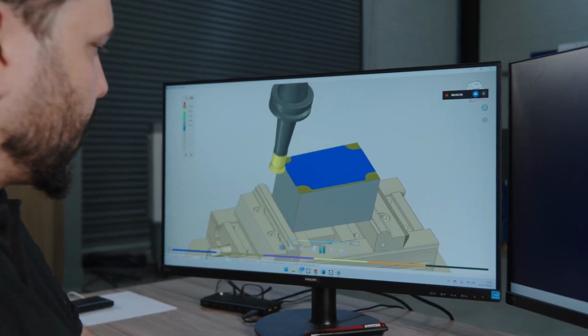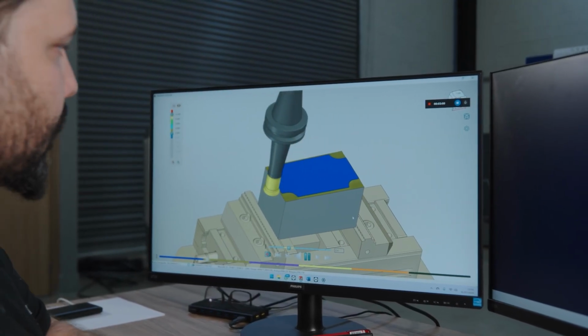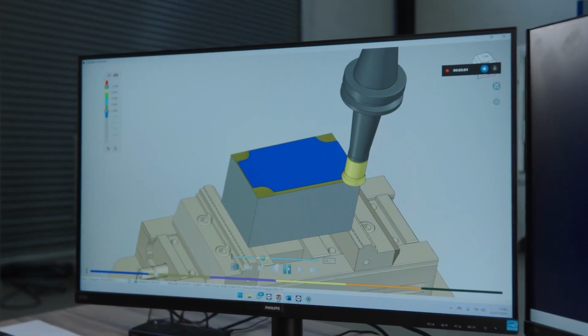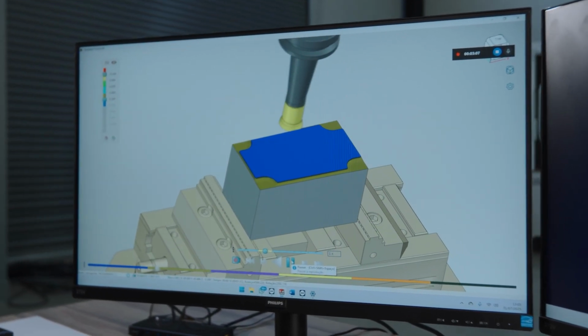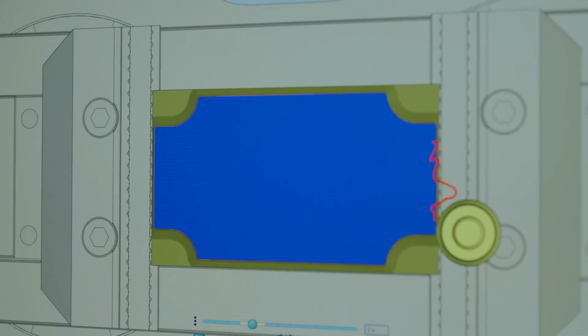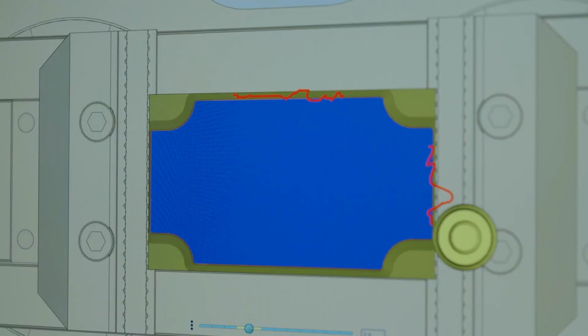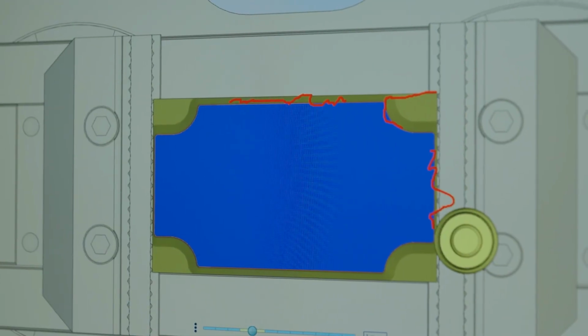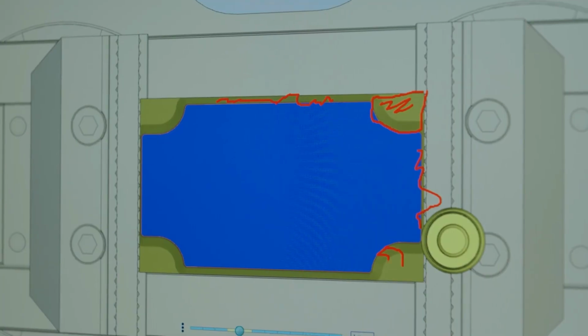Now let's look at a contouring process where this problem is even more serious. Come with me. Here I have a contouring process. You can see that here this problem is even more serious for a few reasons that I'm going to show you now. Notice that in this part I have an area with very little material to be removed. I have an area with a bit more material to be removed, and I have a very large area of material to be removed here in the four corners, so that I don't have problems when I reach areas with a lot of material to be removed. It's normal for us to lower the feed rate taking these large areas into account, and that way the tool works slowly throughout the entire path of the part.